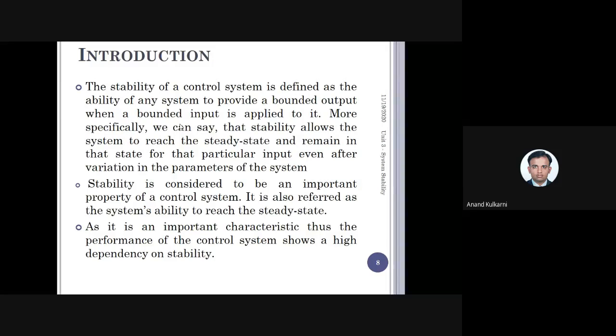So the bounded input is either a step input or an impulse input, because an impulse input also goes to one fixed value and becomes 0, but it will not continuously increase or decrease with time. So you can only think of two standard test signals now, that is step input or impulse input, not parabolic or ramp input. And sinusoidal input is not considered here.